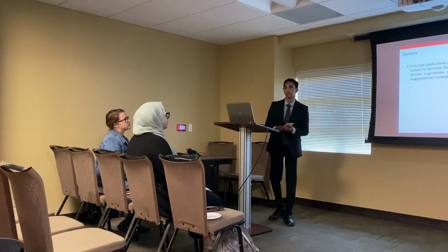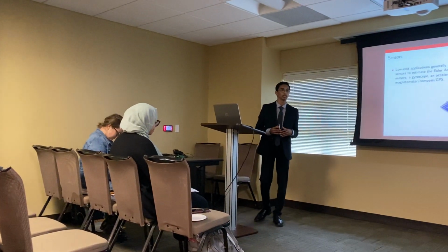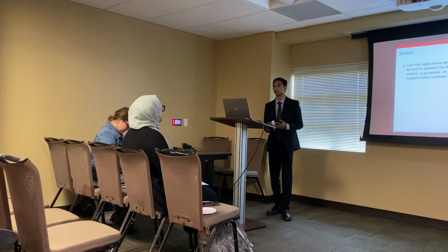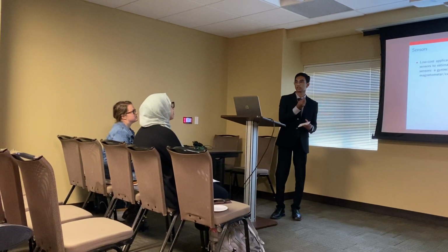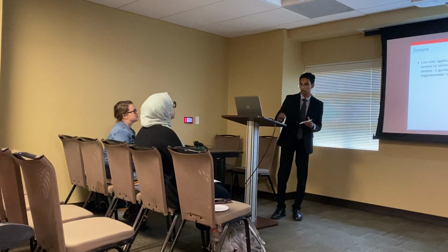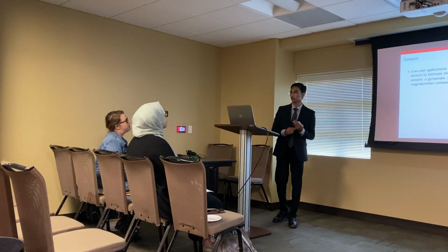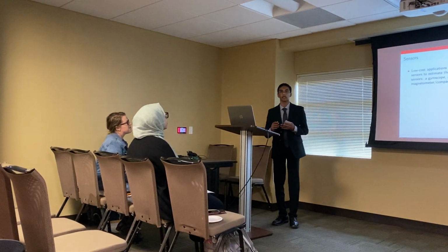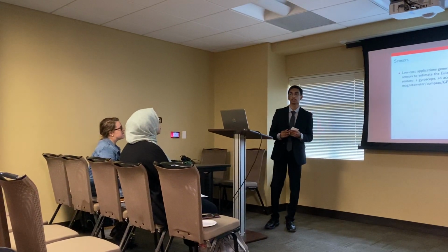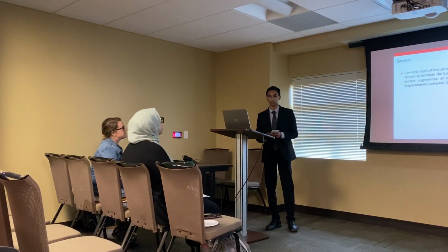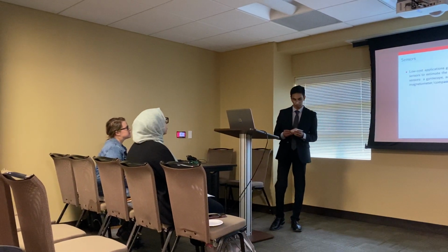The next bit of background information is about the specific sensors I used in this project. For most low-cost applications, they use what are called inertial measurement units, or IMU sensors. This is the specific sensor I used on the project. IMU sensors are basically a combination of three sensors. They have a gyroscope, an accelerometer, and for indoor applications, either a magnetometer or a compass sensor, and for outdoor applications, a GPS sensor. Since this is a mainly indoor application, the IMU sensor I'm using has a magnetometer.